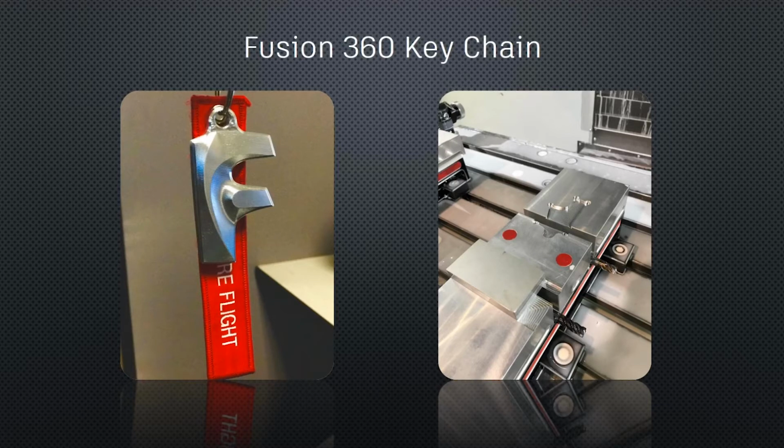So it was pretty easy to hold. But after you start removing material, you start getting some more intricate shapes. And you as a designer, engineer, or machinist have to come up with some pretty unique ways to hold your part, whether that be fixturing, or in our case, we decided to go with a set of soft jaws to hold the part, right?